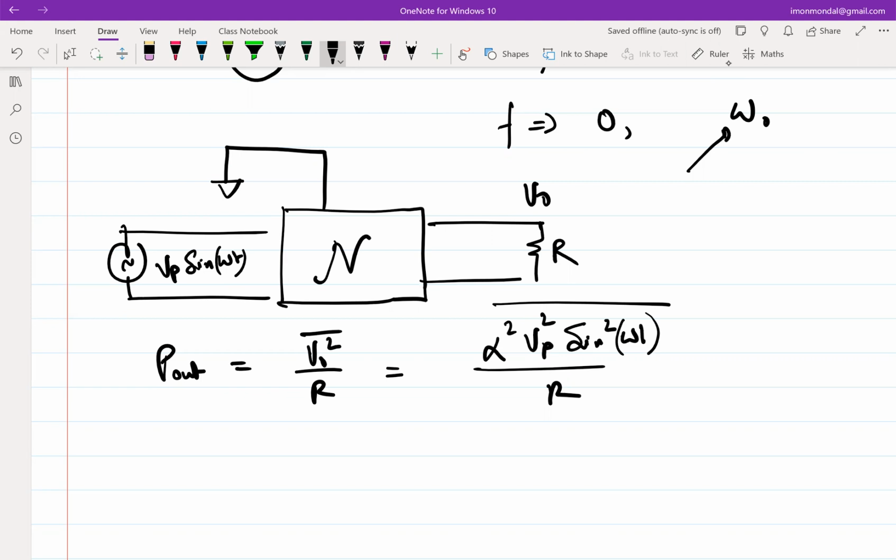In order to transfer power from one frequency to another, you need nonlinear operations, right? If you have an input at omega naught and you want a signal at 2 omega naught, then you need a square term in your network. Without that squaring operation, you cannot get 2 omega naught. You expect the power to be like a sine wave just bigger. Exactly. But that is not happening.